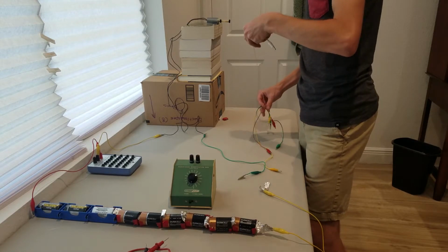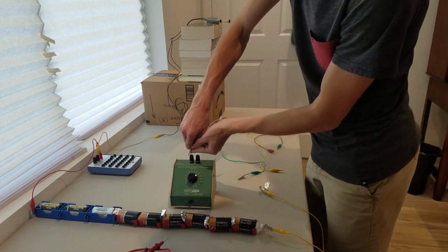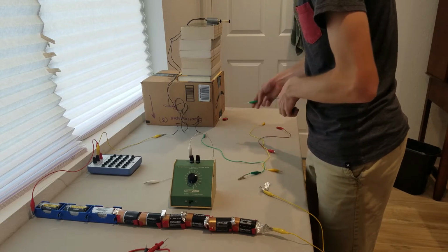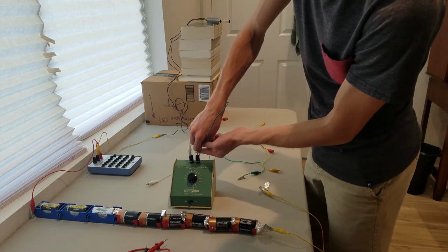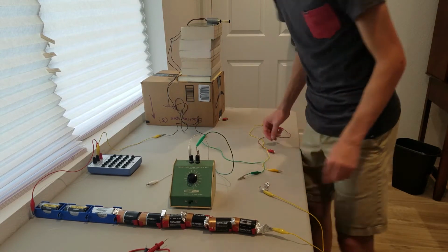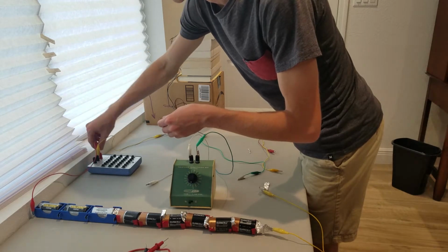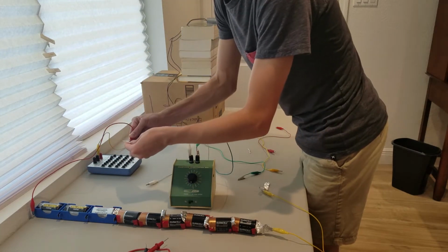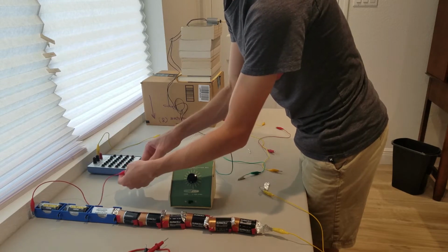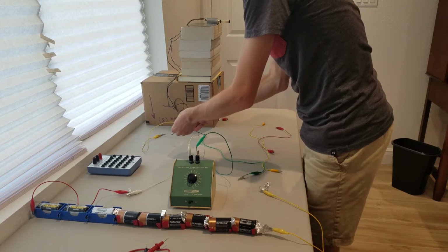Alright, so now for the correct answer. When R2 is placed in parallel with R1, it decreases the effective resistance of the circuit. Using the demonstration, before introducing R2, the resistance of the circuit was 14 ohms from R1 plus whatever the motor's resistance was. When R2, with a resistance of 15 ohms, is placed in parallel with R1, the circuit's resistance is now about 7 ohms plus what the motor's resistance is. This is because of how resistance values are calculated when in parallel.